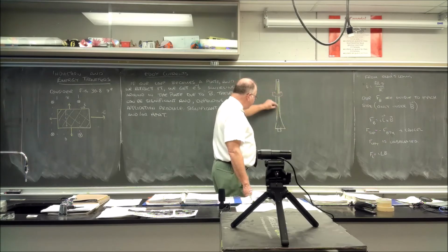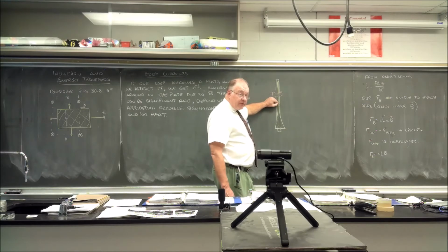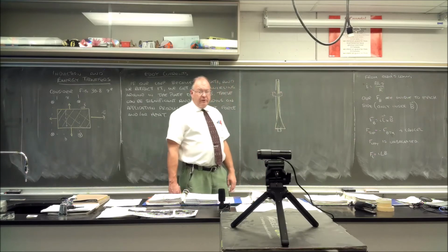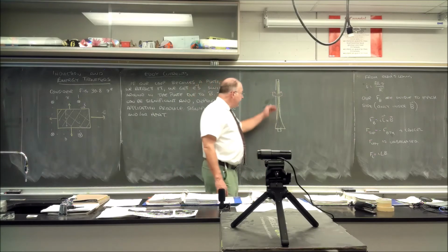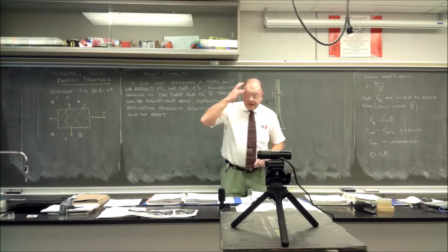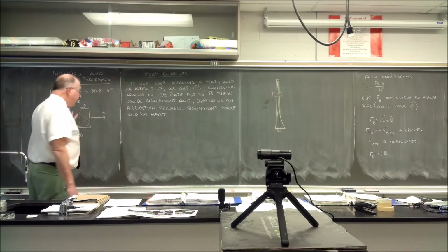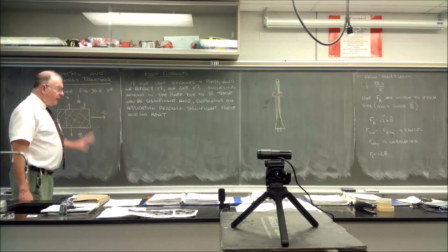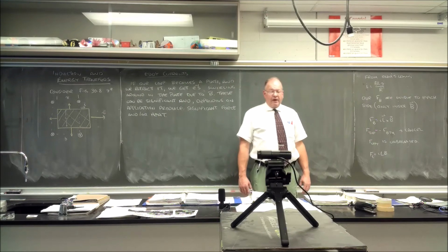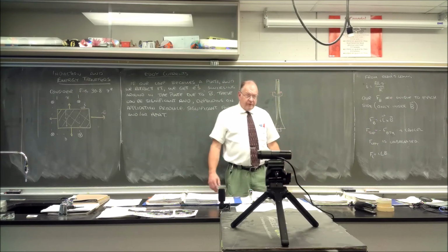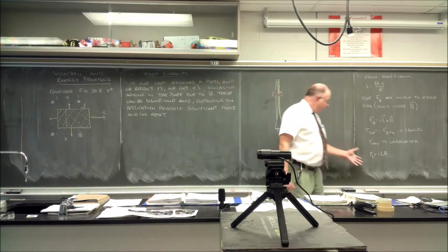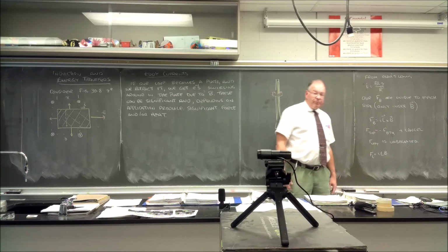So as you come against the plate, you induce pretty impressive eddy currents, because this thing is a non-trivial mass. There's probably a dozen people on it. So this is big stuff. And as you come down, the magnet is sweeping across this plate. And therefore, in any particular region of the plate, it's changing the flux very aggressively. And this is going to produce a pretty impressive potential. I wouldn't want to hazard what the number is, but off the top of my head, it's got to be hundreds and hundreds, not thousands of volts. And what that does then, based on what I just wrote, is we have a force here that's going to be a function of what's being generated, which is going to be pretty impressive.